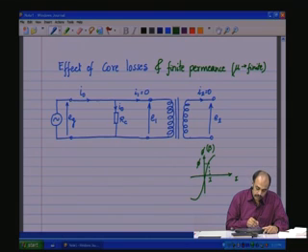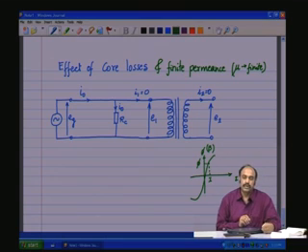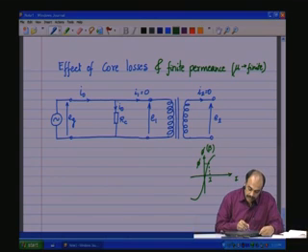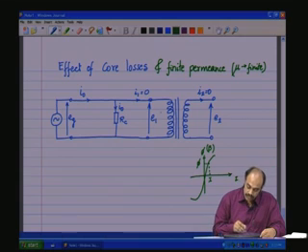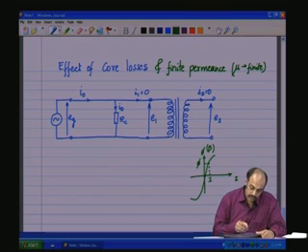That current is also to be drawn and diverted to the flux producing component of the equivalent circuit, and I1 should still continue to be 0 because this ideal transformer is not going to take any current to set up the flux.